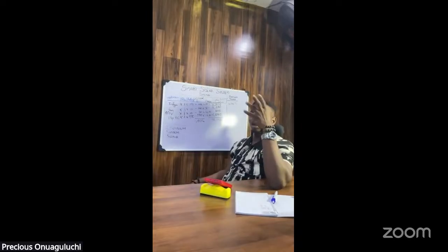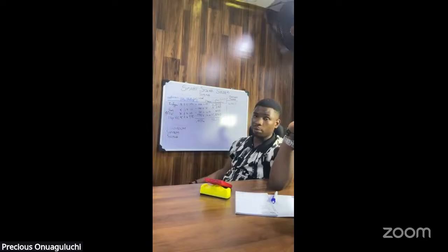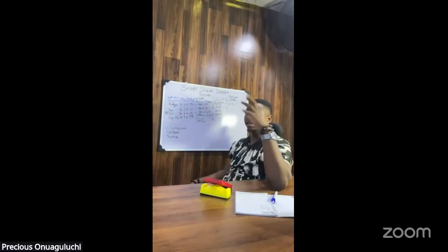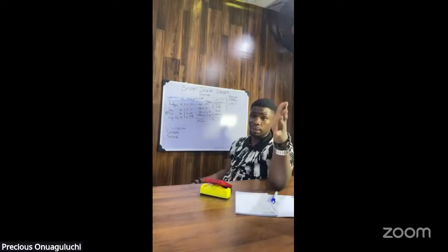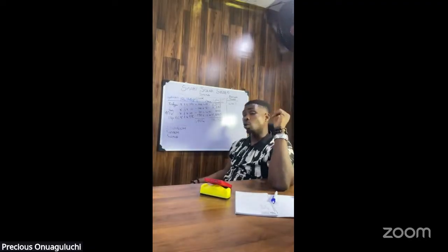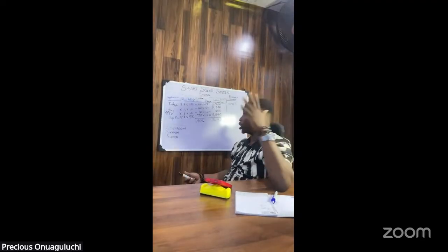So in Nigeria, we always assume that every day will be sunny because we have a wonderful climate. But when you're doing system sizing, it's inadequate to design a system that will go down after 1 day if there's not sufficient sunlight. So it's always good to calculate with 1.5 days of autonomy, or you can even do 2.